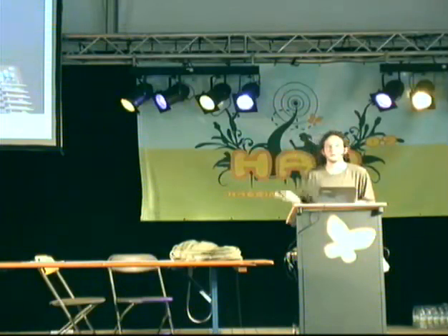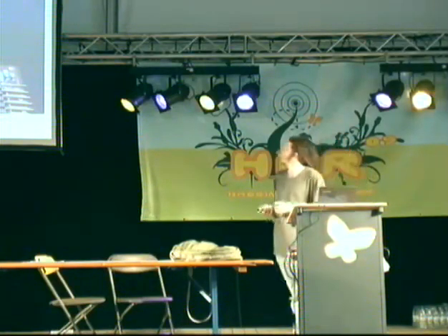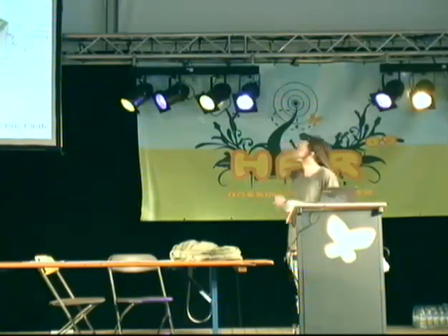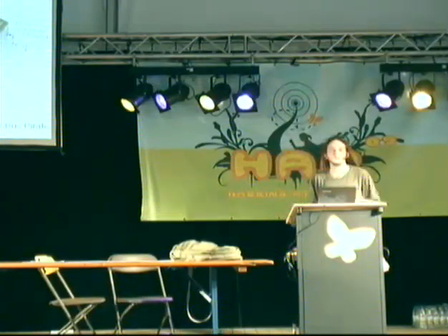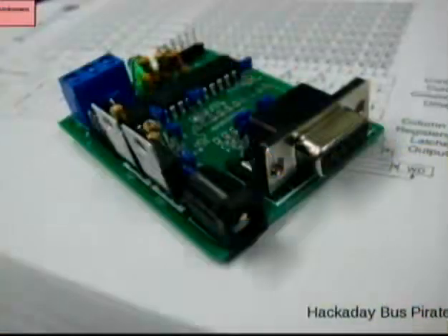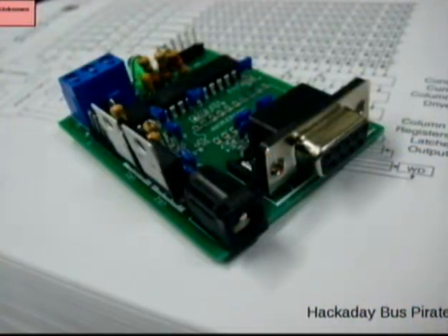You just run the commands out, and you say, I'd like the contents of memory, please, and it gives it to you. You can use the Bus Pirate to do this, or I designed a board to do it as well called the GoodFET. And in either case, you just plug it in, you send the command to read the memory chip, and for I2C it lets you.